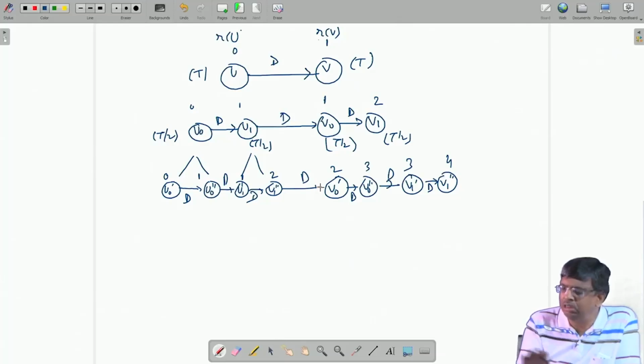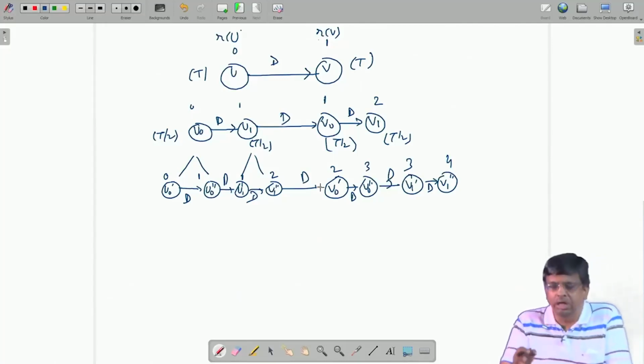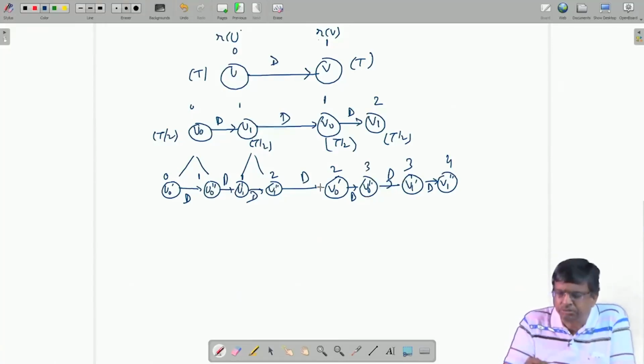These delays were not in the circuit originally. Okay, these delays were not in the circuit, I am adding from external world. This is called forward path pipelining. There is only forward direction. In forward direction, I can go on retiming, I can bring in delays from outside, okay, again from outside, and the critical path reduces. This is called forward path retiming.